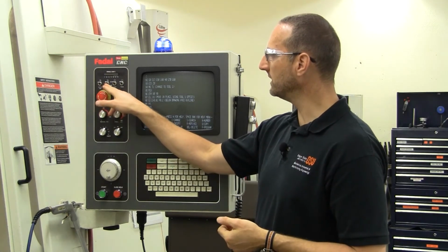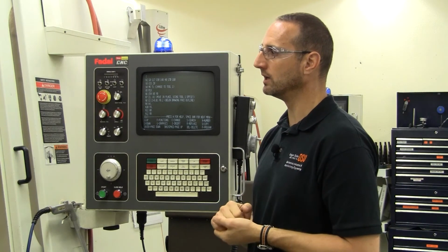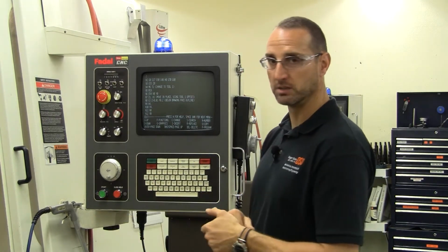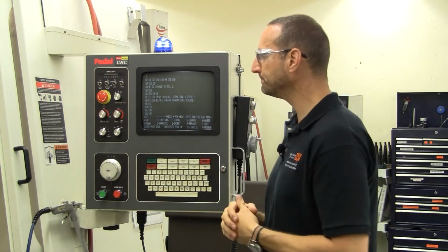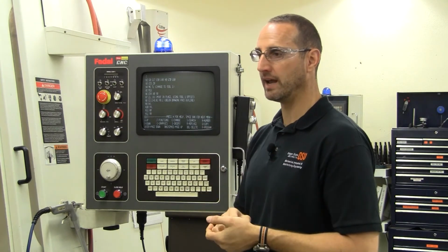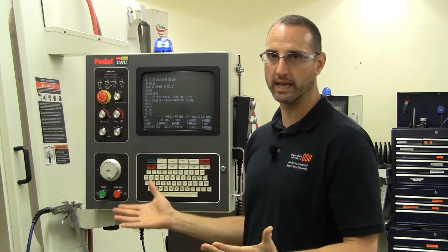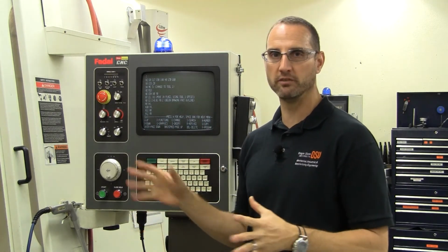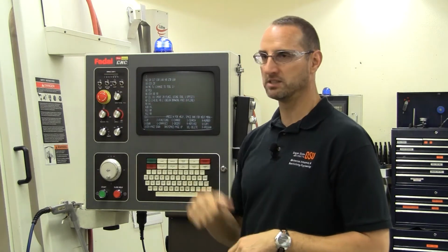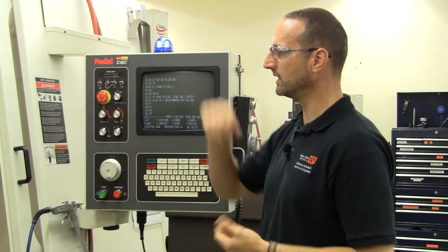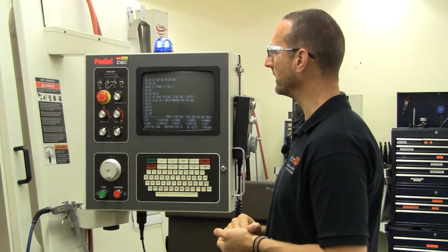So quite often we program our code down in this shop to have optional stops after every tool change, which will allow you to go in and check, make sure that the previous operation went appropriately. So we usually flip it on, and at every tool change we can stop and check it. Now if you're running multiple parts and you've already gone through and you know that the code is running good and your fixtures are all good, at that point it's a good idea to flip that off because you know the machine's going to work out fine. So you flip that off and let it run through all of the program.